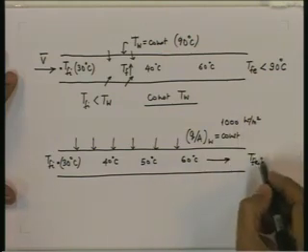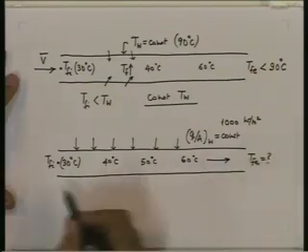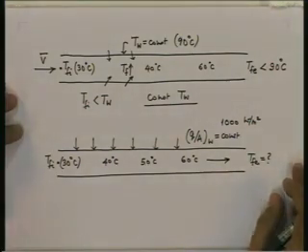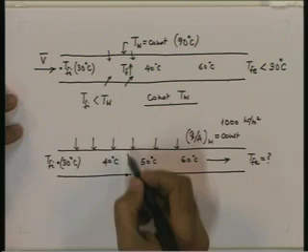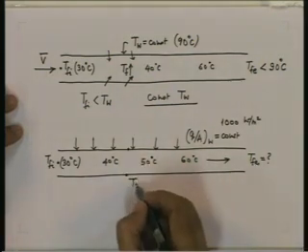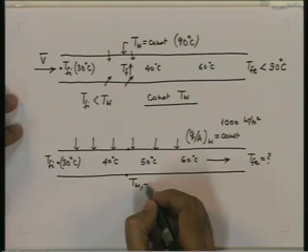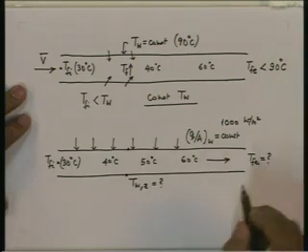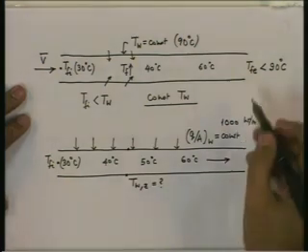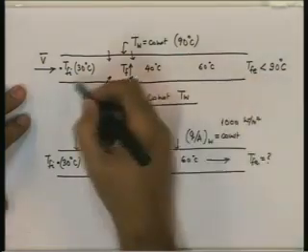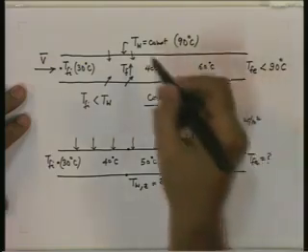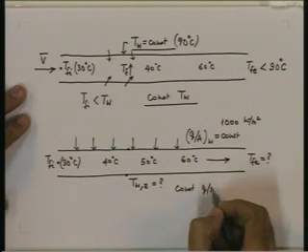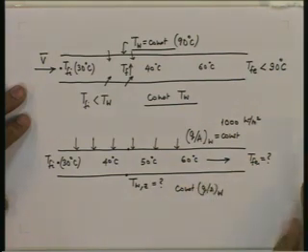What is the exit temperature? There is no limit. It will have to be calculated based on the area and the amount of heat flow. The wall temperature will also need to be calculated. It will vary along Z. We will have to determine what it is. Exit temperature will also have to be determined. Here, the fluid temperature will have to be determined along the flow and the exit temperature, but the wall heat flux is maintained. This is the constant wall heat flux situation.